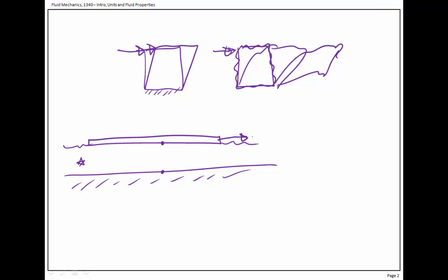So if this thing is moving, let's say it has some velocity v, this top molecule is going to have the same velocity as the plate, right? But this guy is going to stand firm. So at, like, a little time after having moved down this way, we get this velocity profile, as we like to say, and that right there is sort of the shear profile that's going on.